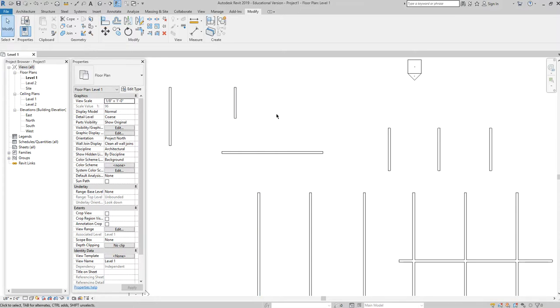All right, I'm going to hit undo, Control Z, align, AL. So the way the align command works is you're going to establish first where you want your objects to align to. Okay, so I want my objects to align to this side of this wall. Click. So I establish a datum point, and that datum point is marked by a blue dashed line. You're going to notice down here at the bottom in my shortened command line, it says, please select an entity to align. It will move into alignment with the reference, right? So again, my little shortened command line down there is telling me what to do. So now I click on this side of that wall, click, and they perfectly align with one another, right?